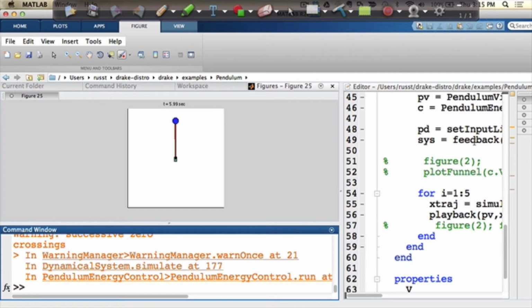Yeah, I think that would work fine as long as you have the property that you're doing only LQR when you get to the top, and you're doing something else away. I mean, the problem is your LQR gains might do really big things. It might actually be hard to mix those in a soft, good way, right? Your LQR gains might be asking for a lot of torque, let's say over by the origin, and your energy controller is actually trying to give just a little bit of torque. So it might actually be non-trivial to mix those in a good way, right?